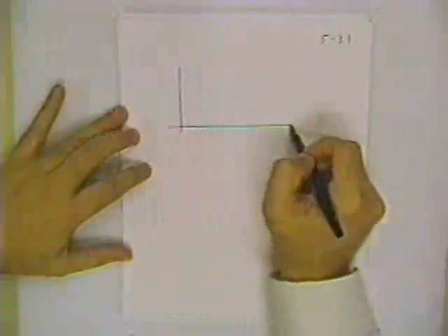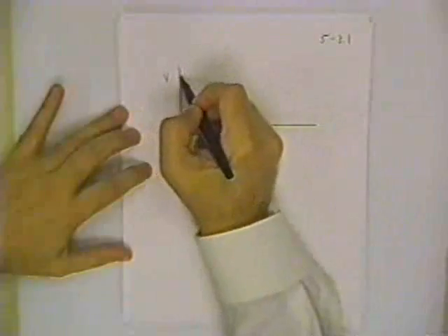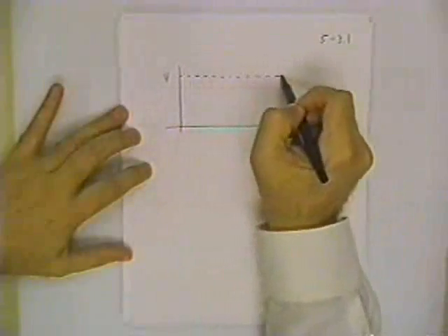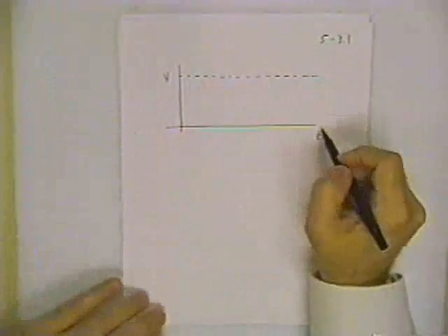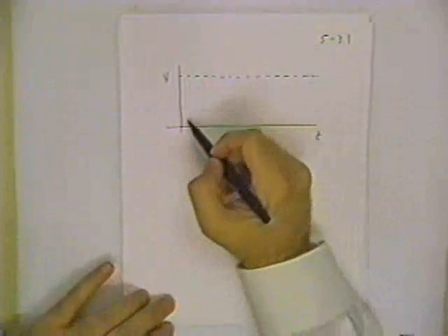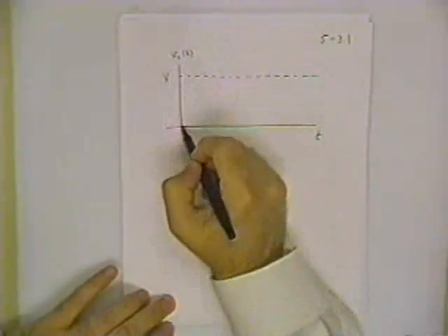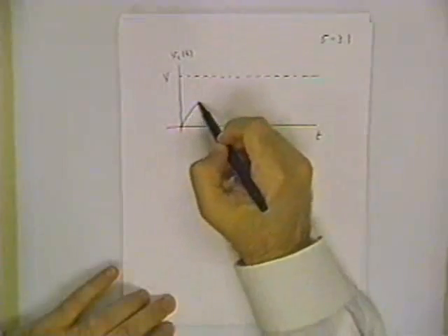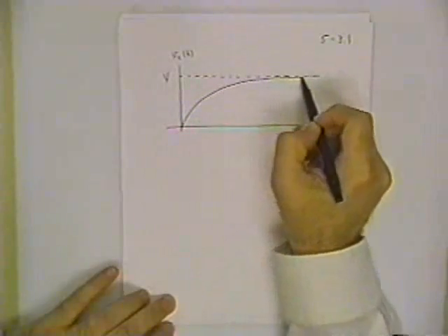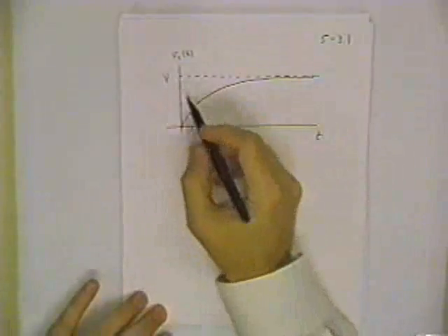And if we look at the sketch of this, we'll also see how the time constant comes into play here. For the capacitor voltage, for a charging capacitor, we've got an eventual steady state voltage of V, but we have to wait an infinite amount of time for it to actually get that large. Vc starts at 0, so this is Vc of t. It starts at 0 and builds up, getting closer and closer, asymptotically approaching the final steady state value.